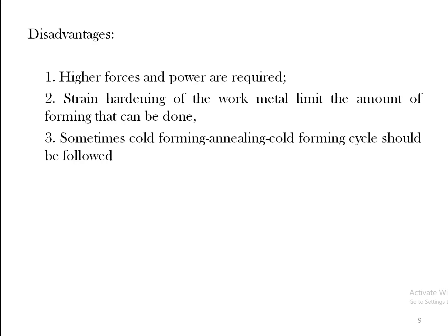Now it also has some disadvantages. Higher forces and power are required since it is in the cold working condition. It's in the solid condition, so to deform it you need a higher force compared to the hot working process. And the strain hardening of the work metal limits the amount of forming, so it is not possible to cold form all metals.